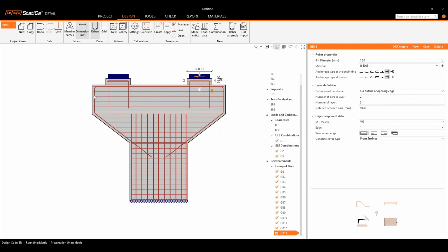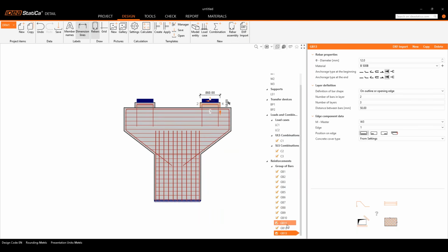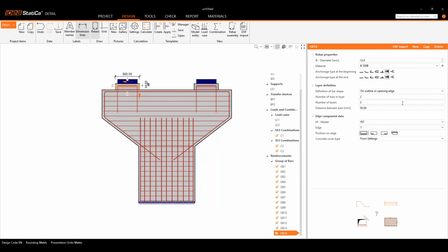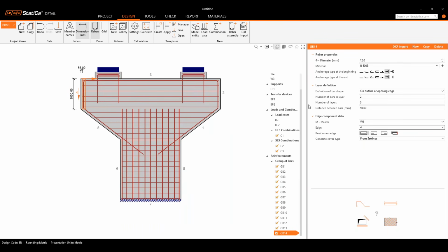So we're going to have to add reinforcement on the transport side. So now I can copy the same reinforcement that I have from here. Perhaps this one. And I'm going to make use of master number one once more. This time, making use of edge number 4. Edge number 4, I have here the length, so I'm going to make some changes over there.